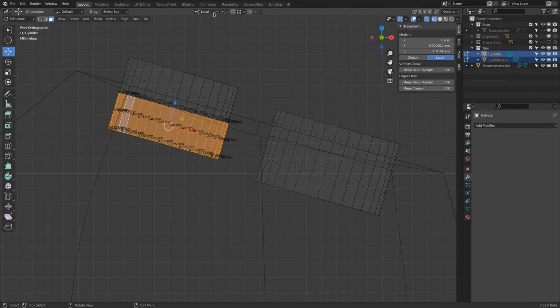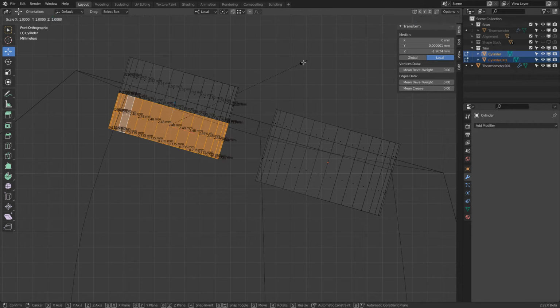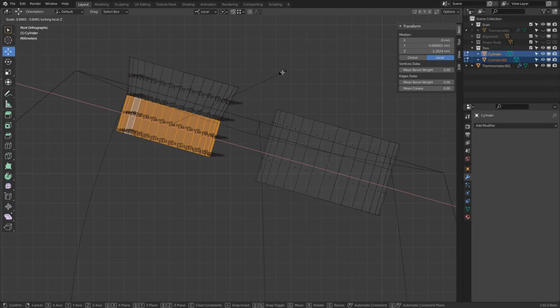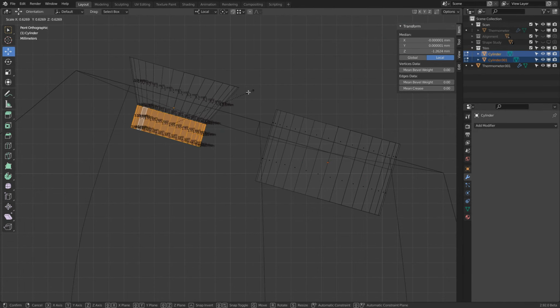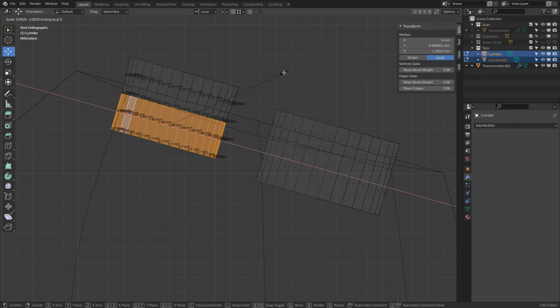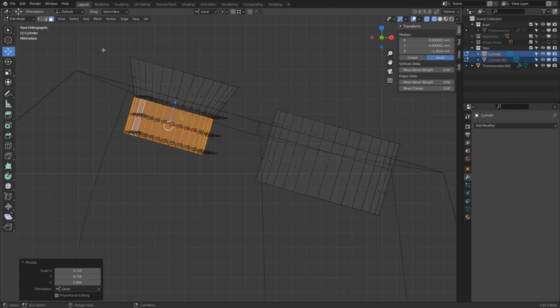And then I can, this important number of scale, S and Shift Z. So what's happening? I scale along X and Y, but I ignore Z. So if I just only press S, you see how this all scales. S Shift Z, maybe like this. There we are. And how much did we scale? 0.7. Let's say 0.7. And then we do this cleanly here, 0.7.